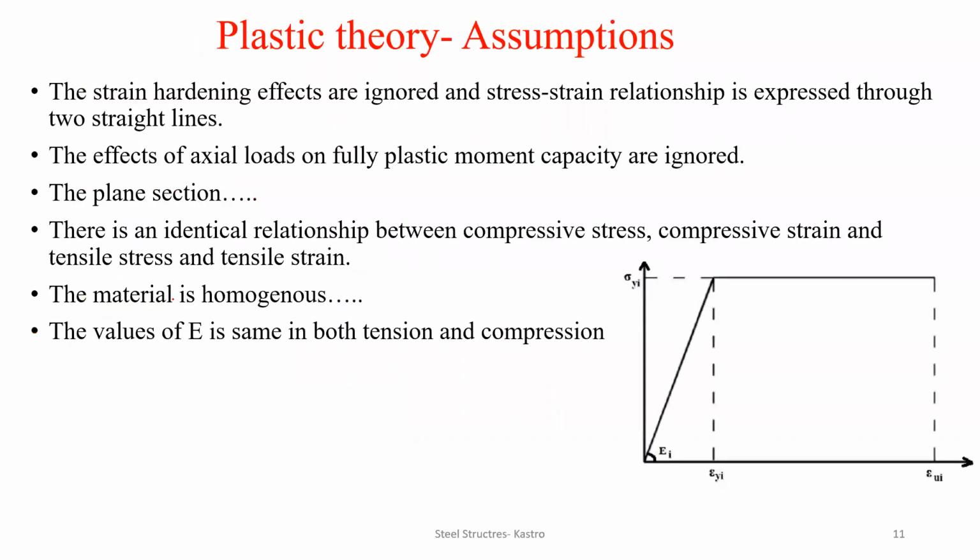Anyways, let's look at the plastic theory. Okay, so before we talk about all these terms, let's look at the stress strain curve of a mild steel. You all know the stress strain curve of a mild steel goes in this way. You have the proportionality limit, elastic limit, upper yield point, lower yield point, ultimate load point, and breaking point, right? So this is the original stress strain curve of a mild steel portion.